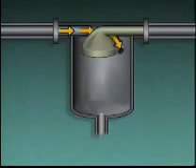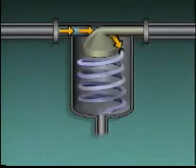As moist gas enters the demister, it begins spinning. Because liquids are heavier than gases, centrifugal force causes liquid to separate from the gas and hit the shell. The liquid runs down the shell and out through the liquid outlet.